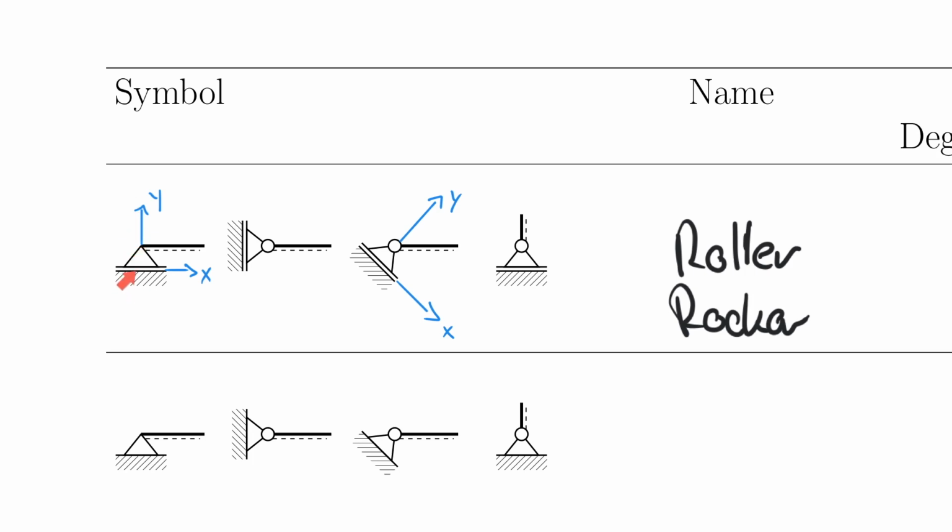So notice that we can move in the x direction, we cannot move in the y direction. And yes, this picture is not super clear. It prevents upwards motion and downwards motion. Some people think it could lift up because there's nothing that prevents that. But as you saw, for example, for the railroad bridge, it's heavy enough that there will be no uplift for sure. However, motion in the x direction, no motion in the y direction, and motion is possible in the rotation about the z-axis. And I represent that with these circles usually.